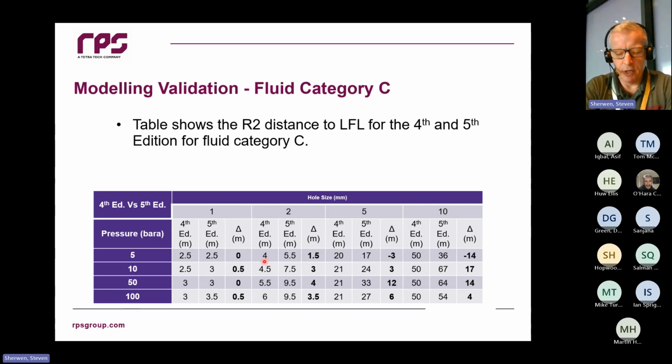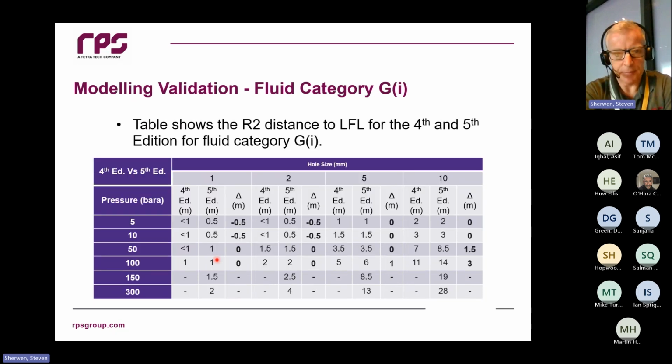But we think that for almost all situations, particularly at these lower pressures at smaller hole sizes, for storage tanks, pumps, things like that, you'd be going to a lot of effort to maybe save half a metre or a metre of zoning, which in the grand scheme of things probably wouldn't be worth the effort of going to all that work in remodelling releases.